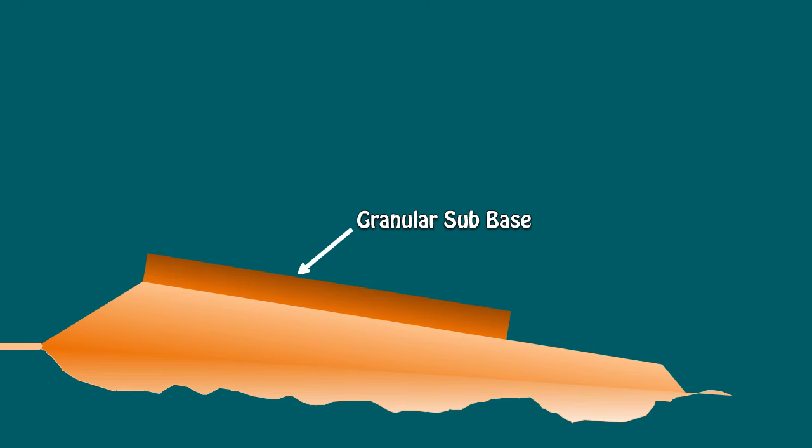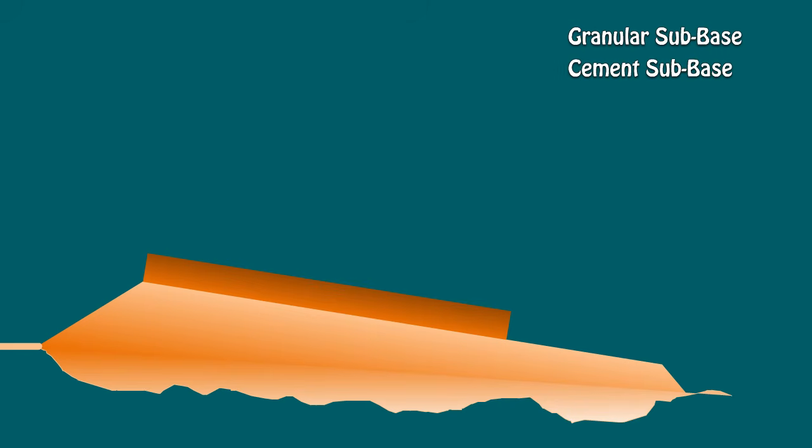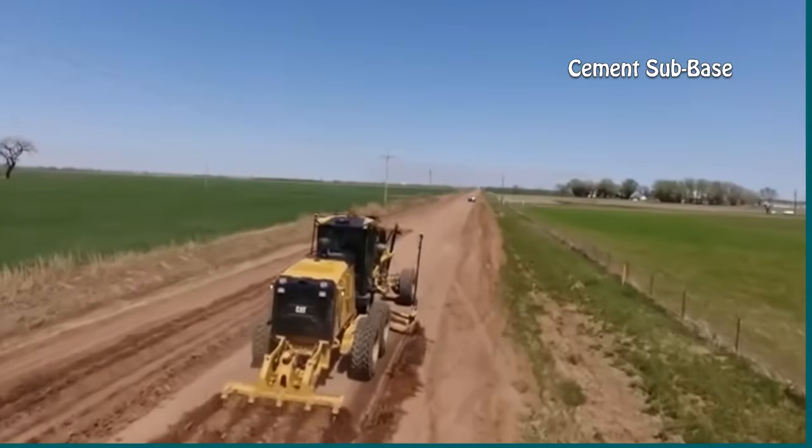The next item of work is a subbase. Most paving relies on supports. The subbase layer is the main load-bearing layer of a pavement. It is designed to spread the load of the paving and any traffic thereon evenly to the subgrade below. The interlock between adjacent particles of the subbase material ensures the ground's ability to carry heavy loads comparatively. There are two different types of specifications followed for the subbase. One is an unbound granular subbase, and another one is a cement-bound subbase.